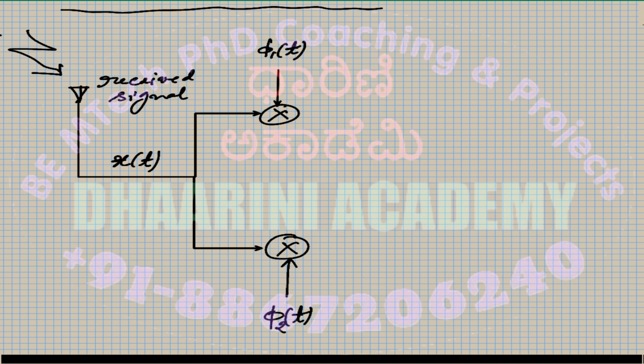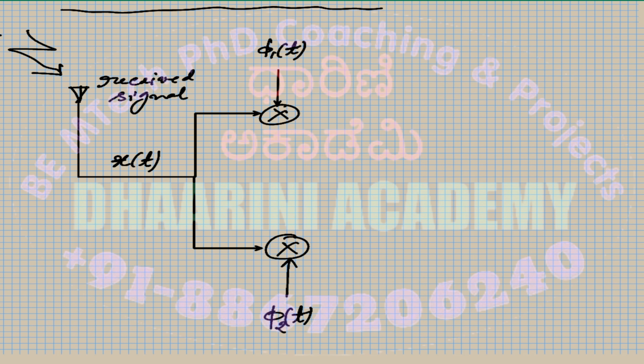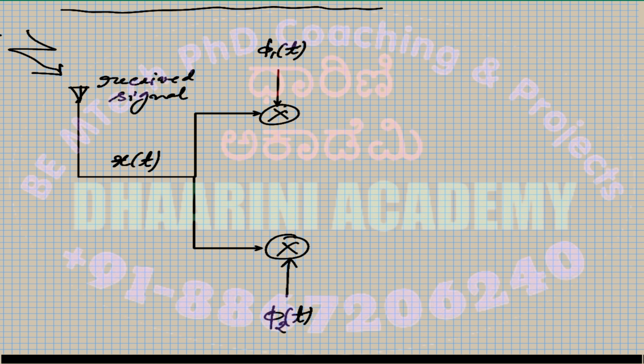In the received signal, we have seen that if you multiply by phi, assume that there was a cos function and phi1 also has the cos here, and when I multiply cos into cos, it becomes cos square of that frequency, and when I square it, I'm going to get a 1 plus cos 2 theta format. So that 1 will give me the original signal back, and the cos 2 theta, the high frequency component, can be eliminated by using a filter.